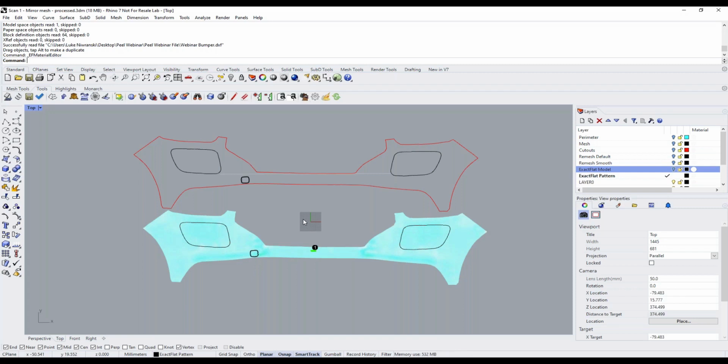If you're working with a very expensive material and it's very critical that you get the absolute perfect part right away, you might choose not to mirror the part. You might want to take the extra time to scan it. That way you have 100% confidence that the 3D model you're working with is a true representation of the part that you're going to be covering. That way when you do the flattening work, you're guaranteed that you're going to have the perfect fit. So there's a lot of different factors that come into play there. The complexity of the part, the amount of time you want to spend doing it, the material, and so on. So unfortunately, I don't think there's any guide that I can offer for when you should mirror your part or not. It would probably be on a product by product basis.